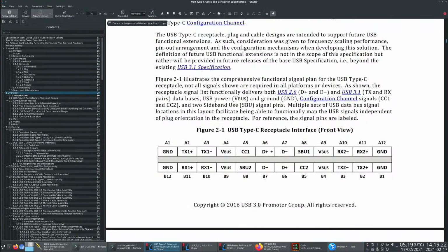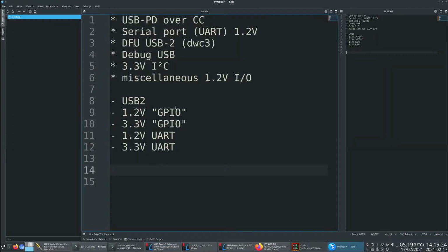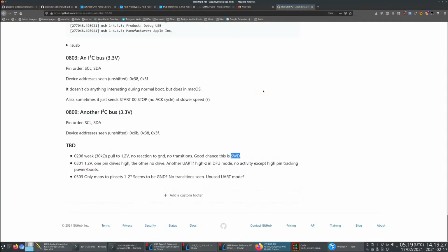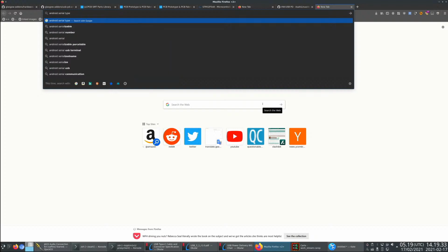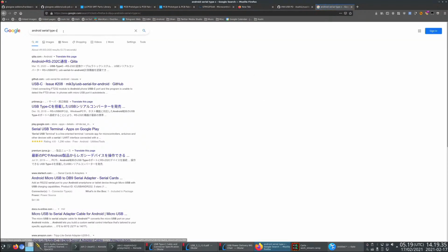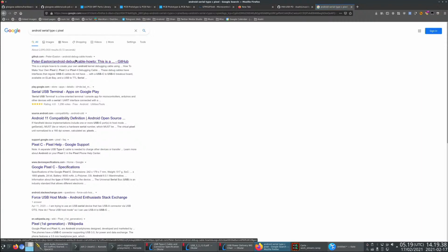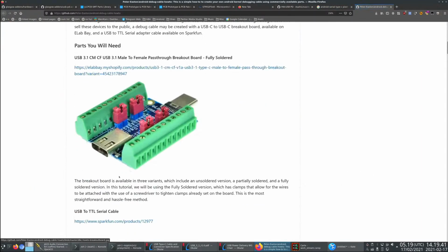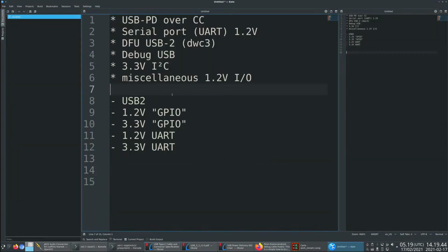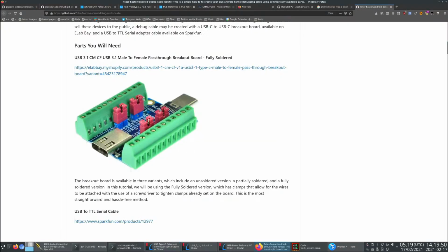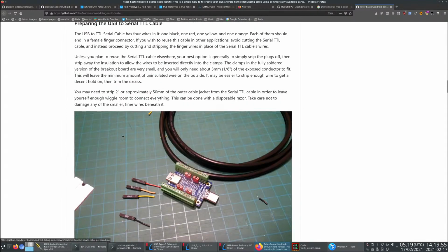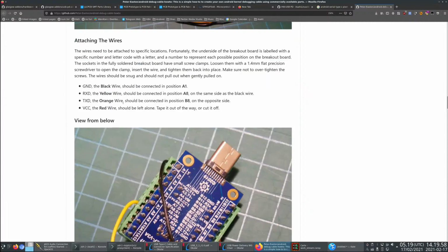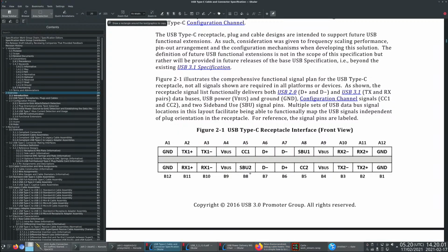So that's about the cables. But if you look at other devices, once you have these features here, there are more devices that do serial port over USB Type-C. So, for example, on Pixel devices, you can get debug on... Oh, by the way, so we said for triggering this on Macs, we need a standard USB PD, so just a single CC line. But if you look at how, for example, some Pixel phones do serial ports, it turns out that what you need to do is you get RxD and TXD on the SBU lines.